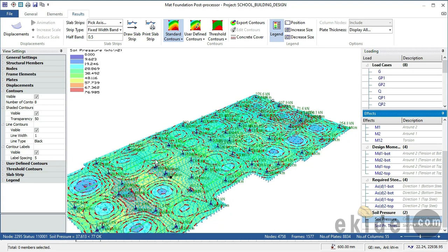So the whole idea, just to be fast, is for you to get the maximum of this and locate this maximum here for the soil. Once this value, which is the maximum, is less than the value here, then your foundation is okay. In this case, we have 76.9 here and 77 here. So the soil pressure due to the weight of the building is less, 76.9 is less than the soil pressure due to the bearing capacity. With this, the foundation is perfectly okay.